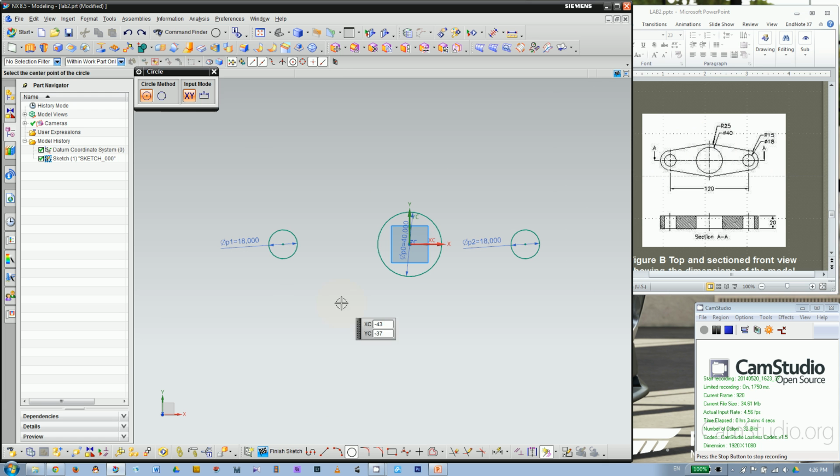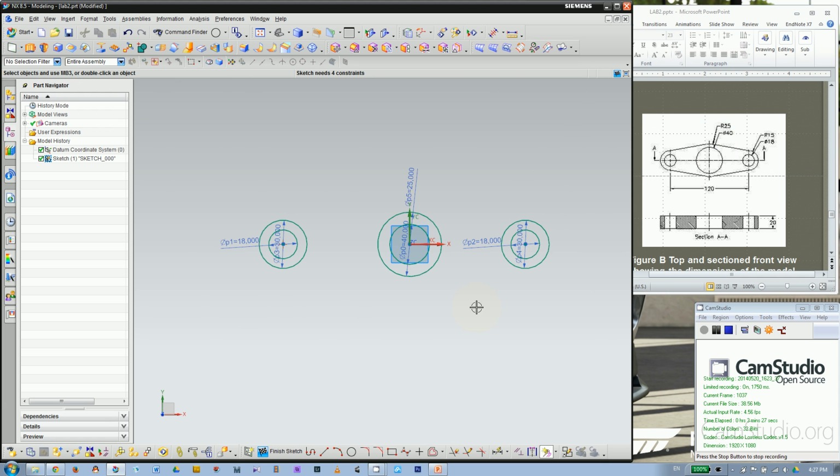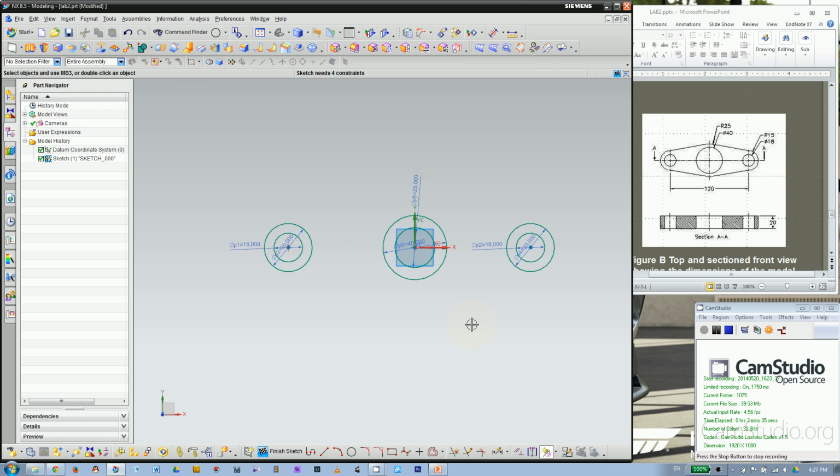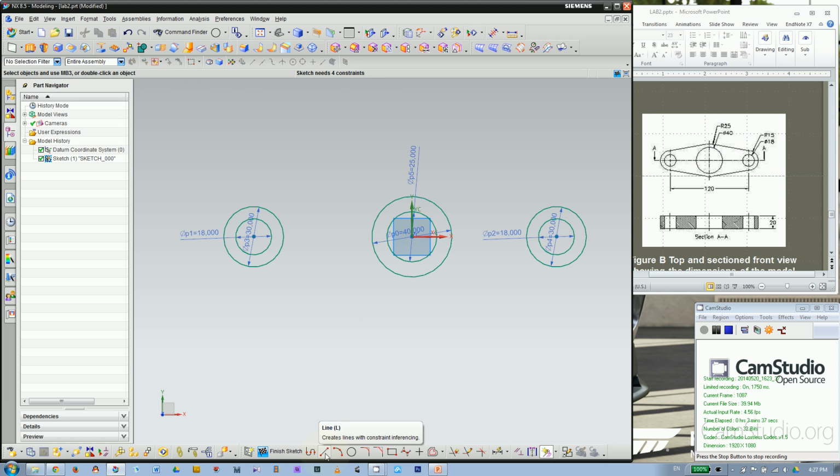Okay, so I'm gonna show you the common way. I'll use 2 circles for the side, radius 15. So let's put this diameter 30. That's also 30. And for the top, usually you can just put another circle with radius of 25, like so. Then you can connect them. I guess this is actually a better way to do it.